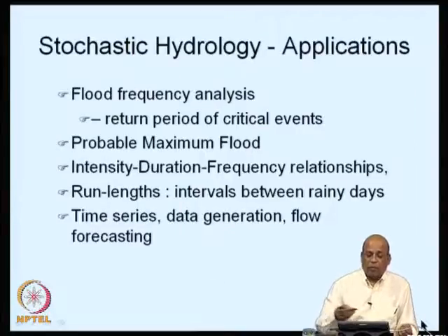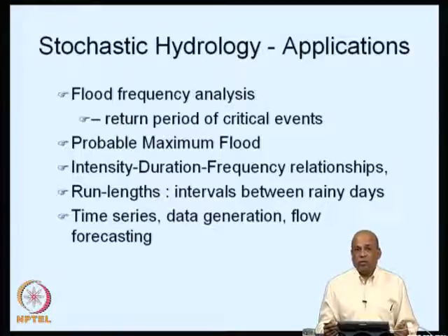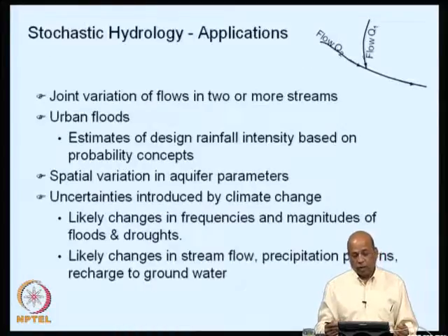Then there are a large number of other problems that we will be interested in. For example, in flood frequency analysis, we would be interested in the return period of critical events. Then we will also be interested in estimating the probable maximum flood, especially when we are designing the reservoirs. Then intensity, duration, frequency relationships for making decisions on flood protection measures. Then run lengths, typically intervals between rainy days. Then time series data generation and flow forecasting, all these are applications of stochastic hydrology.